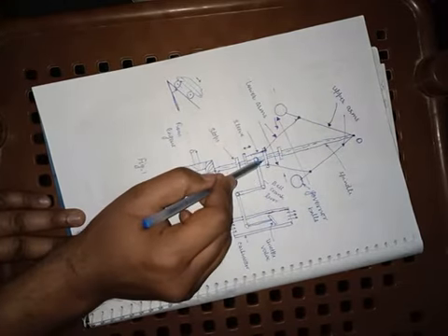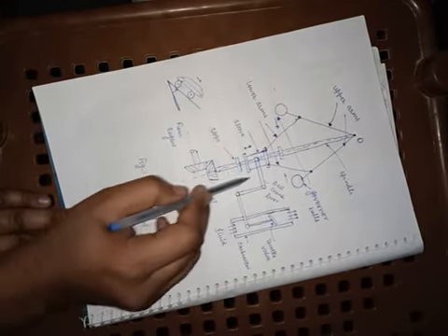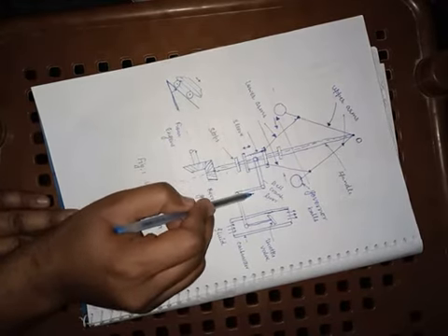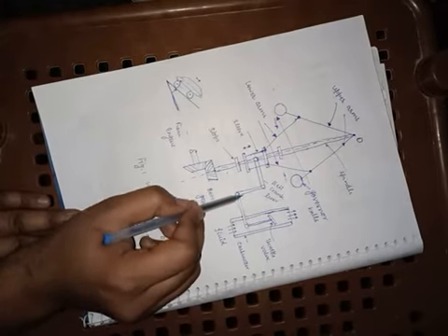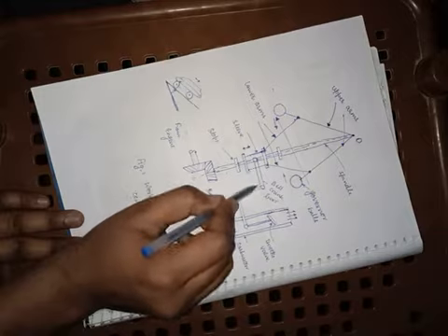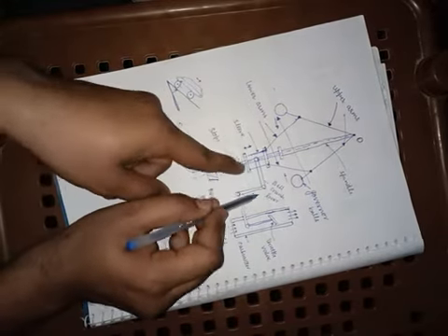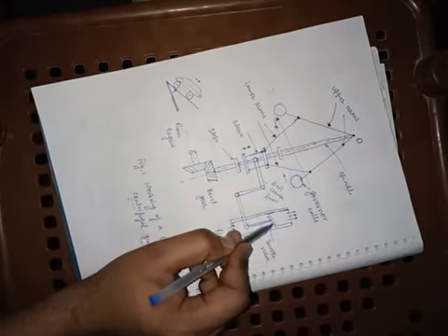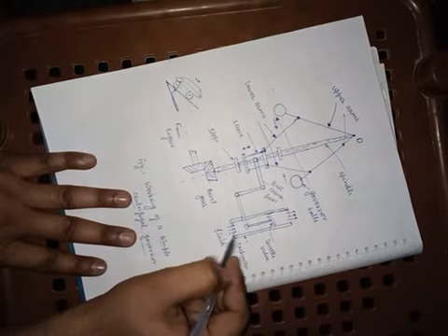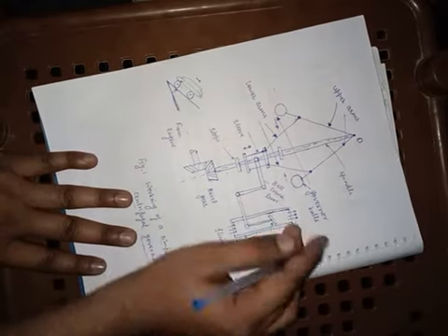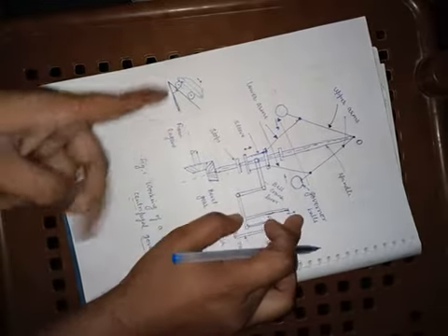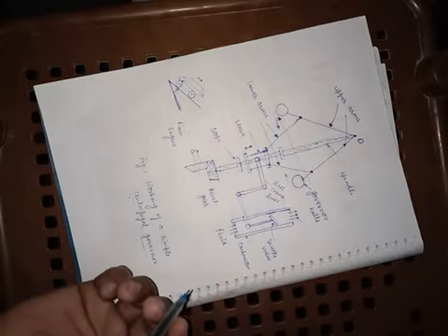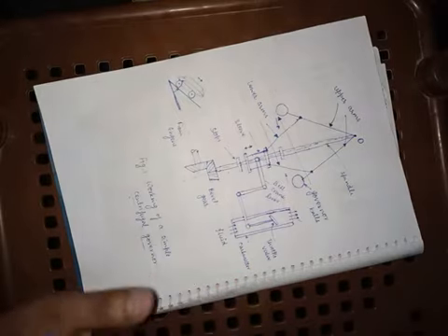And then, as soon as the motion is communicated to this bell crank lever, this bell crank lever will turn the throttle and adjust it in such a way that it will increase the supply of fuel. So it will open and increase the supply of fuel. As soon as the supply of fuel is increased, obviously fuel burns in more quantity and then the speed increases. This is case one, how it is controlling when the vehicle is moving in the upward direction. So to maintain the same speed, it increases the throttle and maintains the power supply.